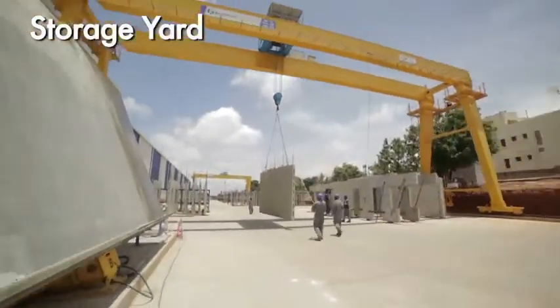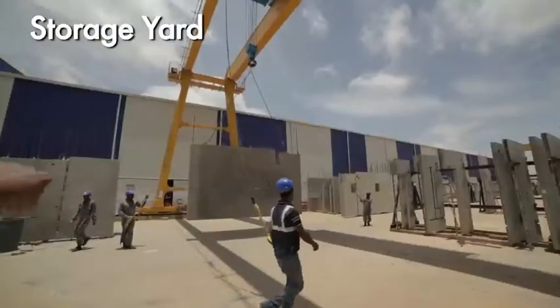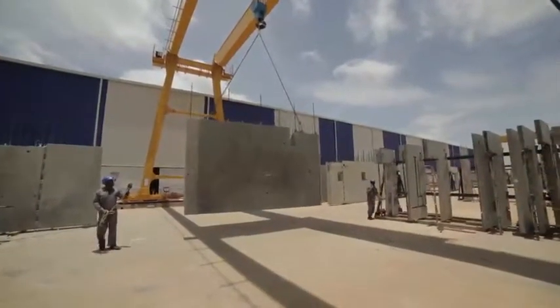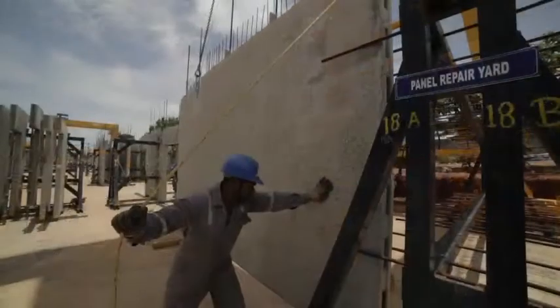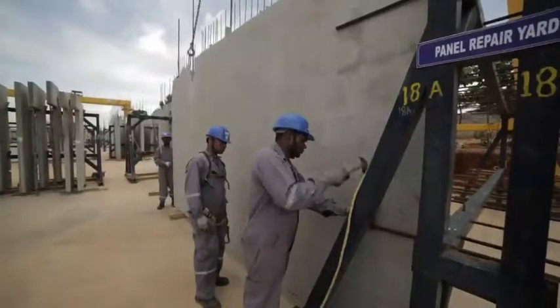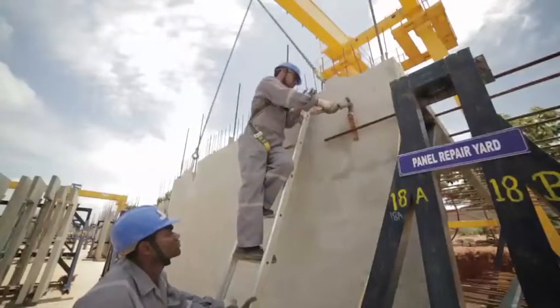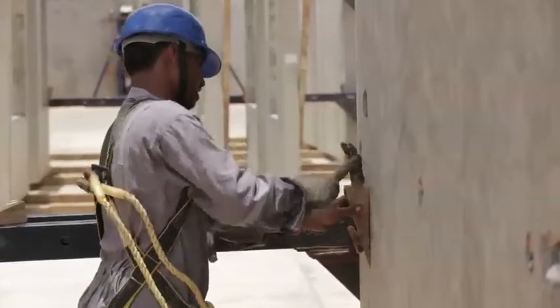Storage yard. Wall elements are stored vertically on A-type racks. Slabs are stored horizontally over wooden blocks and segregated depending upon type of elements. They are temporarily locked to prevent movement during lifting.